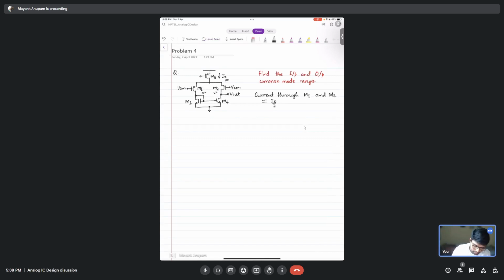In this case, what is ensuring both the currents should be the same are M3 and M4, because they are a current mirror. On top of that, these two currents should be equal. Who is making that possible? As you correctly said earlier, these two transistors, M1 and M2, are also identical, and they have the same voltage at their input, VCM, right?